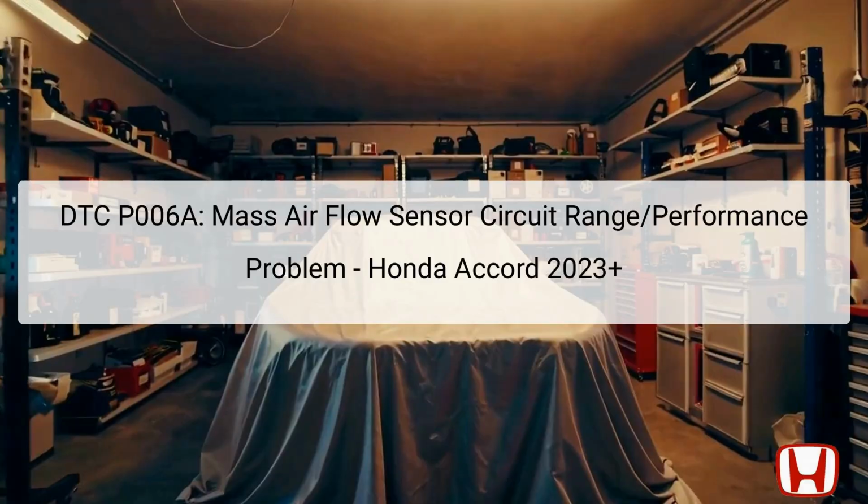The diagnostic trouble code, DTC P006A, indicates a mass airflow, MAF, sensor circuit range or performance problem in the 2023 Honda Accord. This code is triggered when there is a mismatch between the intake air amount measured by the MAF sensor and that estimated by the manifold absolute pressure MAP sensor. Such discrepancies lead the powertrain control module, PCM, to recognize an anomaly and subsequently store this code.